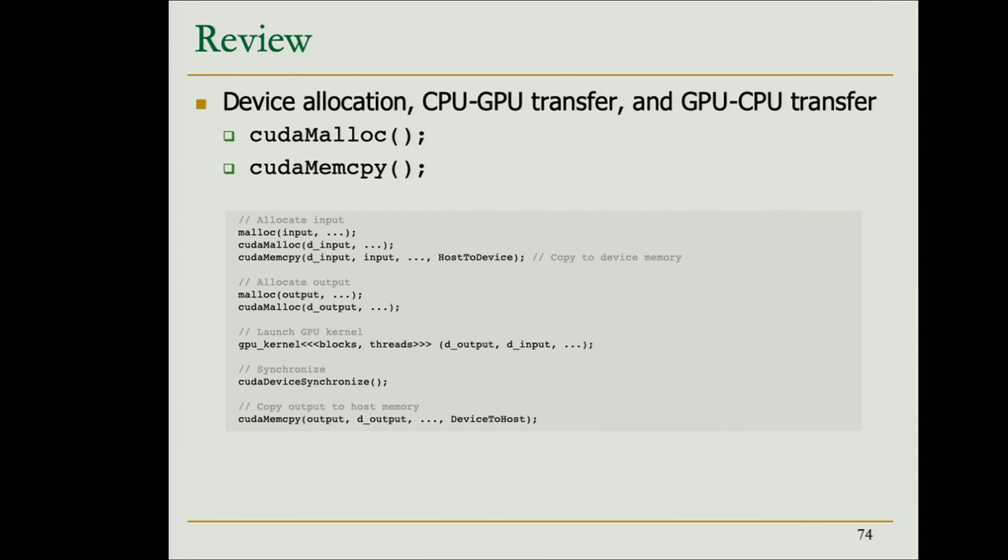Okay, let's talk about collaborative computing. Are these new features? They started to be available in CUDA maybe 2 or 3 years ago. What they enable us is to have a tighter collaboration between the CPU and the GPU. Or if we talk about OpenCL, a tighter collaboration between the CPU and other devices, which could be 2 GPUs, or 1 GPU and 1 FPGA, or multiple combinations like that.